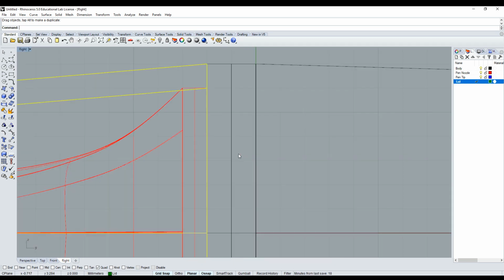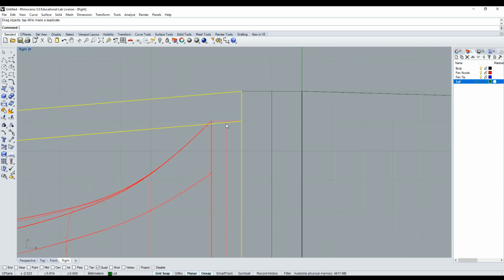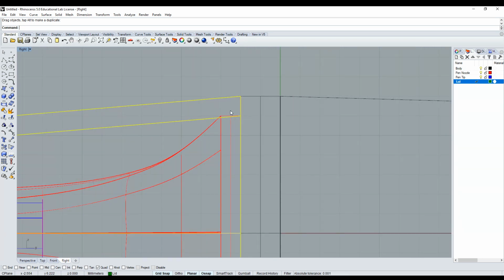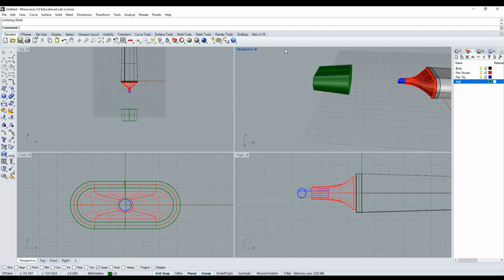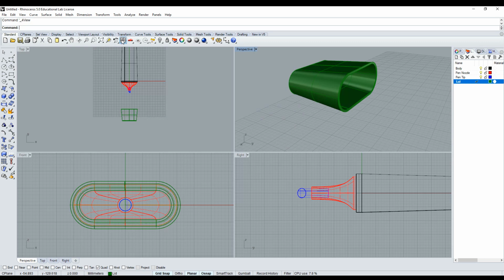Now, in reality, you could see, just zooming in here, that it wouldn't work because this piece of plastic is intersecting with the body of the lid. So I'd need to adjust. I will adjust it. Let's do it. Let's go back to before I capped it. So I'm going to shell this object from this face, and the thickness this time, I'm actually going to make 0.7 of a millimeter. From there, enter. Lovely. Okay, so that distance there is 0.7, whereas before it was 1.